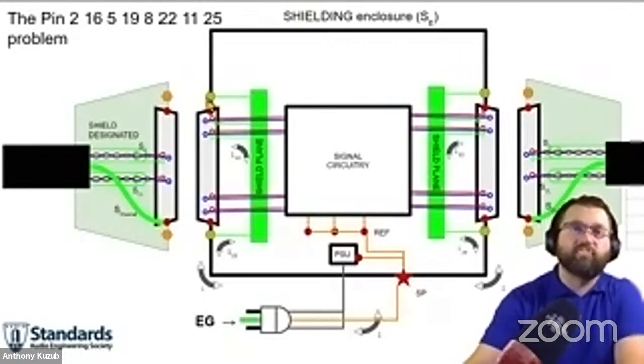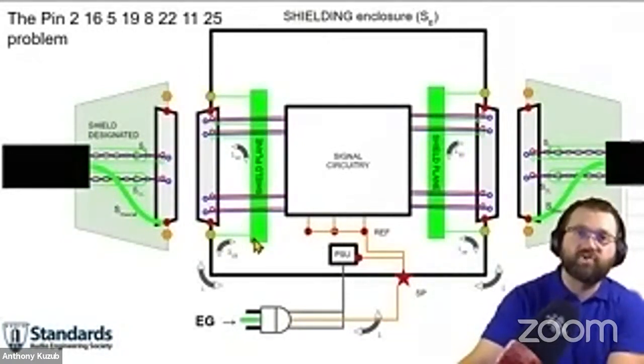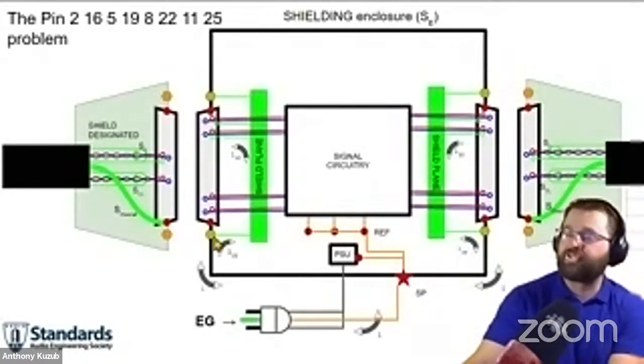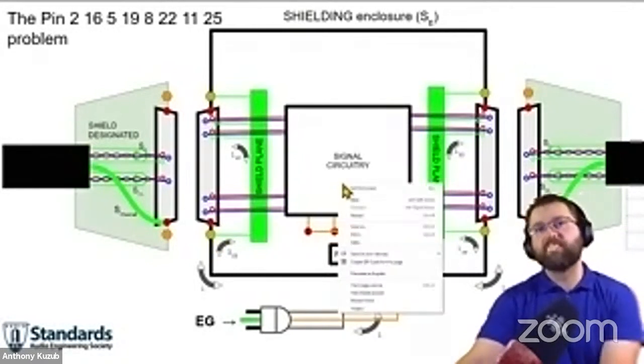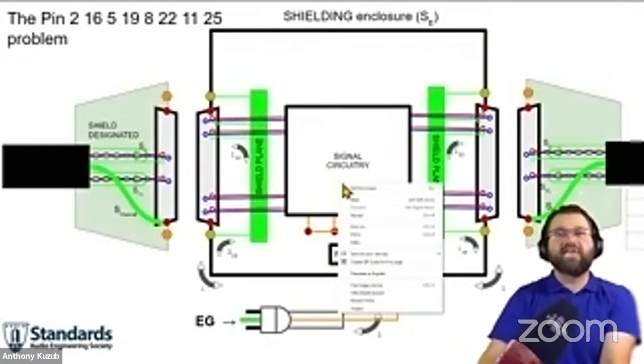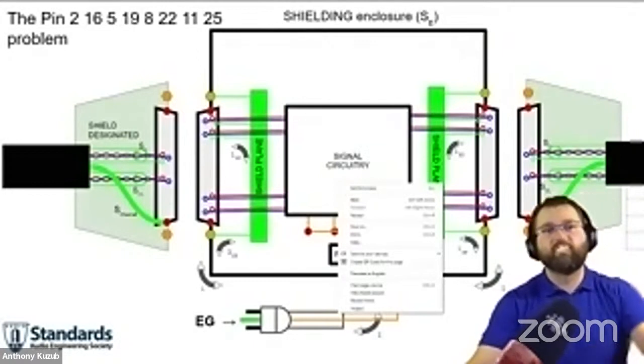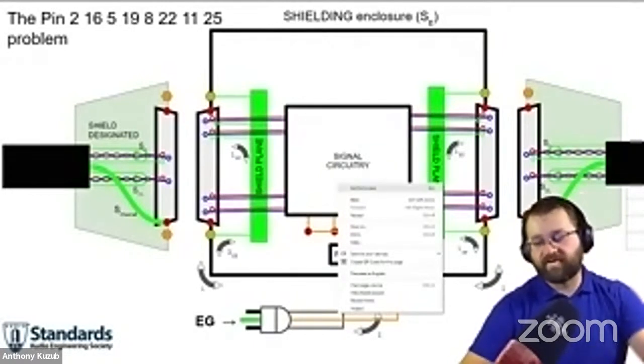And what we're recommending and what has been discussed is this design technique of using a shield plane that bonds it to the chassis as soon as possible. In some cases, it's not completely possible to have shield plane circuitry designed that way, but in future designs, we hope engineers ultimately do something like that.